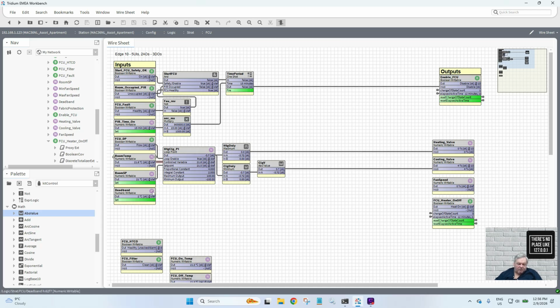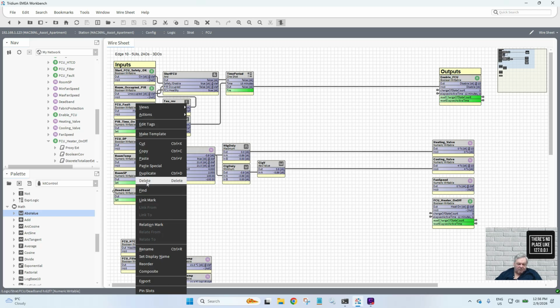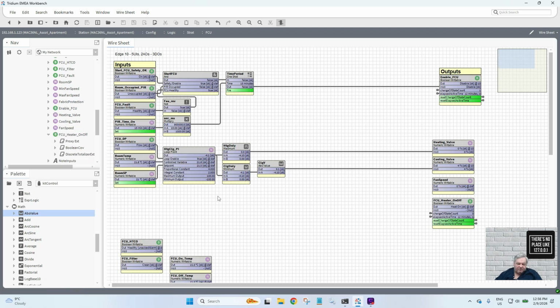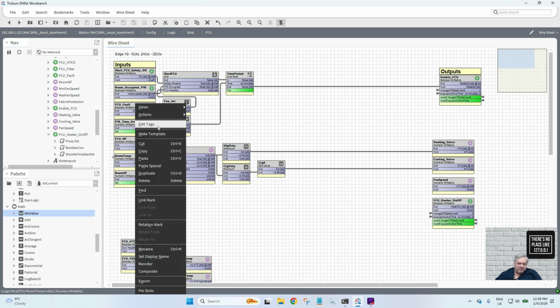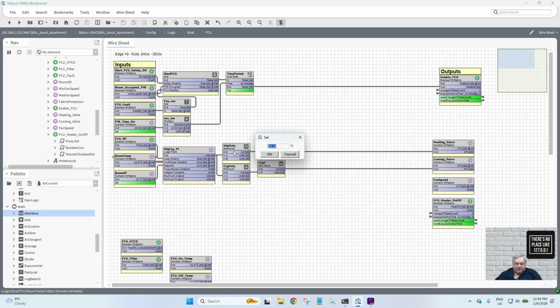So I think we're going to forget our deadband and actually use that in our logic. And the hotter it gets in that room, so let's say it's 24 now, really hot, lots of people in there, that's opening up higher, and it will continue to open up higher.